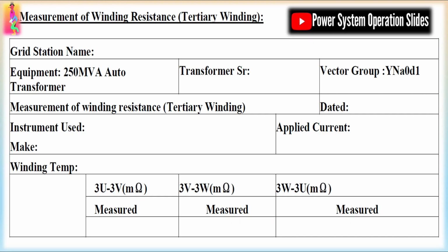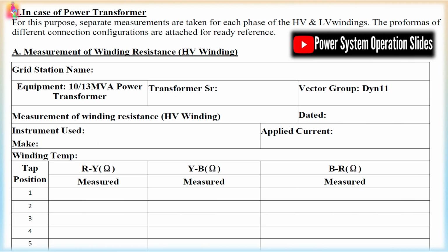Significant variations between taps can signify wear or oxidation on contact surfaces within the tap changer or internal bus bars. Such defects, if allowed to progress, may lead to arcing or failure during load transfers. Detailed analysis of tap-specific resistance values supports targeted maintenance of the tap changer and helps avoid costly unplanned outages.